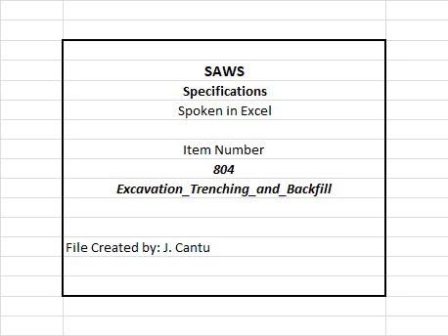S. When unsuitable bearing materials such as water, silt, muck, trash, debris, or rock in ledge, boulder or coarse gravel, particle size larger than 1/3 inch, is encountered at the bearing level, the contractor shall over-excavate and remove such materials to a depth no less than 6 inches below the bottom of the pipe and replace it with a material conforming to the requirements of this specification or as approved by the engineer and/or inspector.